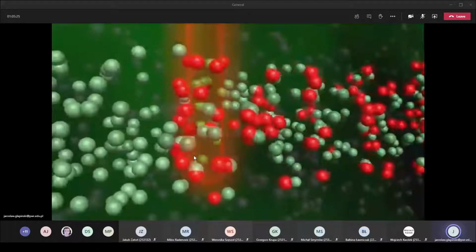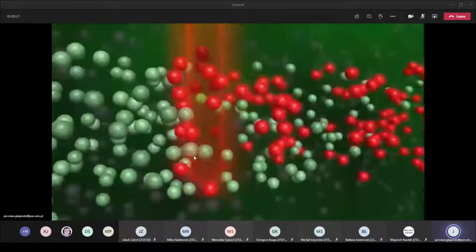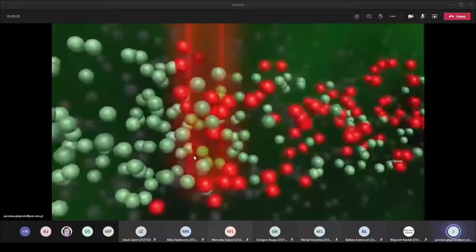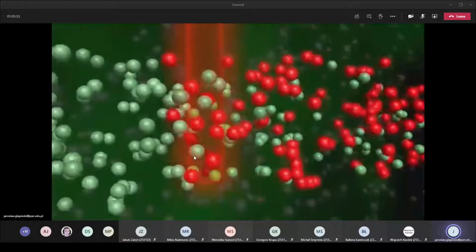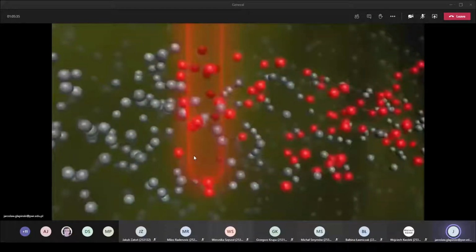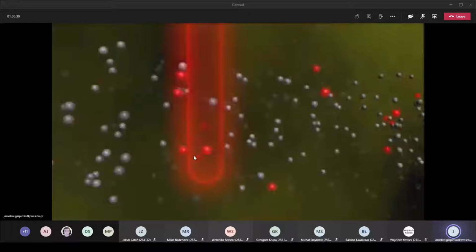And finally, the heat transfer is also affected by the thermal properties of the gas. For example, at the same mass flow, the high thermal conductivity of hydrogen, shown here in green, causes cooling that is 100 times greater than with air. For a precise measurement, it's therefore important that the specific properties of the gas are known and are consistent.